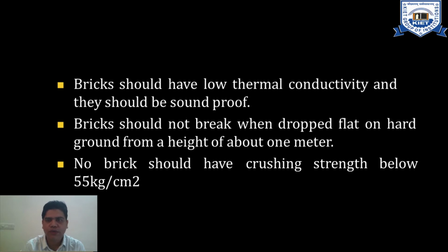Bricks should have low thermal conductivity and they should be soundproof. Bricks should not break when dropped flat on hard ground from a height of about 1 meter, and no brick should have a crushing strength below 55 kg per centimeter square or 5.5 Newton per millimeter square.